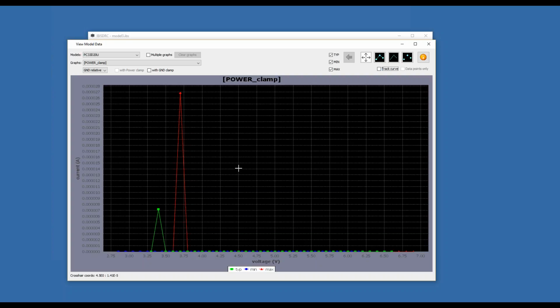You're going to have to go through your process, assign a quality level, and determine what's good enough for you to use and what's not. And again, you could ask your vendor for correlation and say, hey, show me this IBIS model input receiving a signal, something driving through the transmission line into this, and compare it against the SPICE model you made, or show me lab data, show me that the clamping in this input structure and the die capacitance is working the way you expect and properly, right? So that's where the correlation data always kind of comes into play.